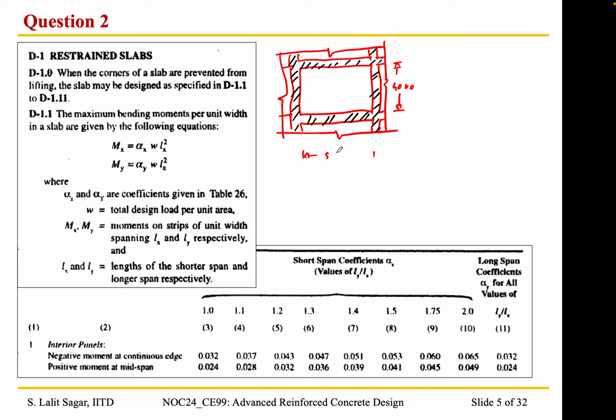Sir, Lx and Ly, sir, clear span or effective span, sir? Length of short span, long span means it is a clear span. You mean for while considering in this table? No, this will be effective span, center to center of supports.